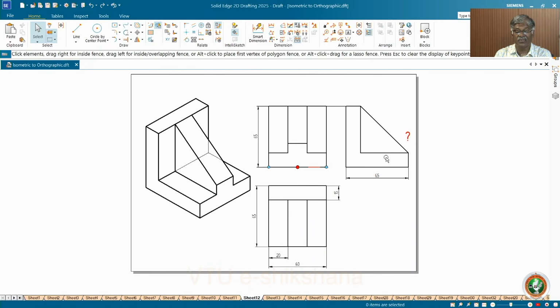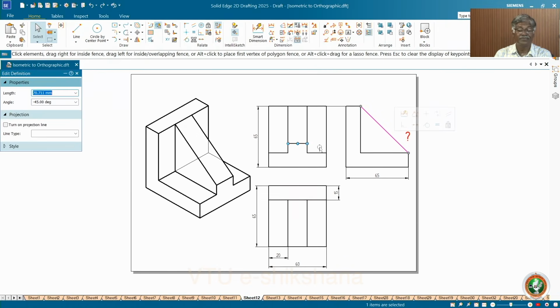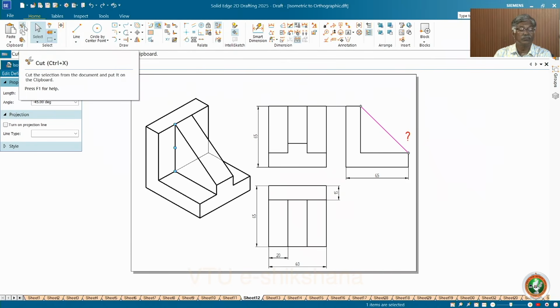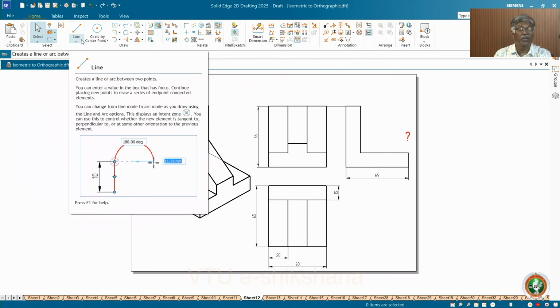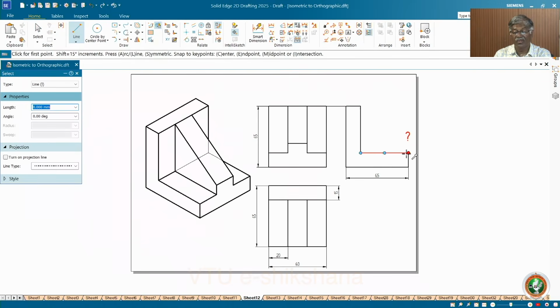And what about this? Definitely there is change here. Okay, earlier we had 10 mm extended here. Here I have to extend 10 mm here, and then join with this and this. So this is how you do it. Okay. Now let me extend this up to 10 mm. So already we have this, so you can just use alignment indicator. You need not measure 10 mm, and then see, this is what you have to do. This refers to 10 mm. So dark this.